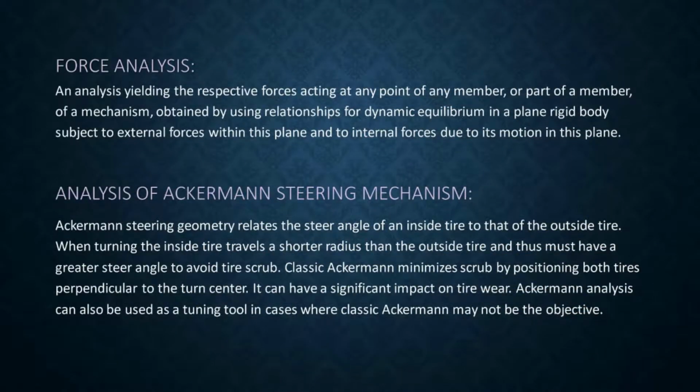We have done calculations based on force analysis on the chassis structure. Force analysis: an analysis yielding the respective forces acting at any point of any member or part of a member of a mechanism, obtained by using relationships for dynamic equilibrium in a plane rigid body subject to external forces within this plane and to internal forces due to its motion in this plane.